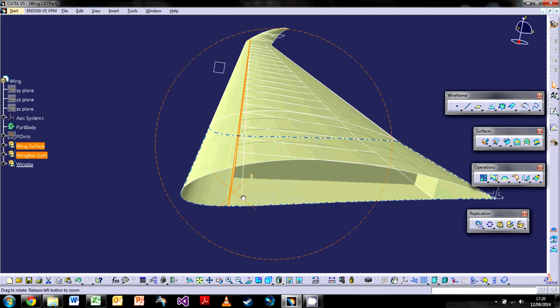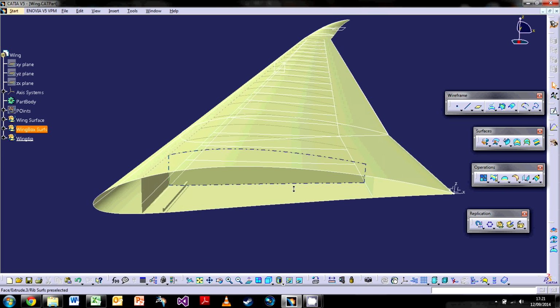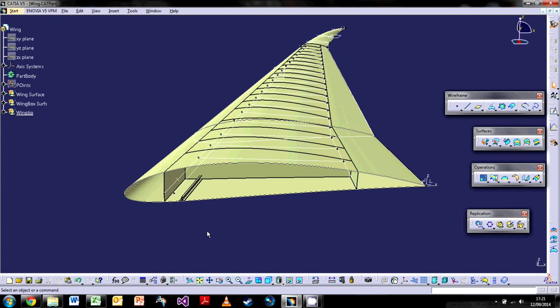Now that's a good way of doing it, because specifically it replaces the links that are from other elements, such as the ribs, the spars. It replaces them explicitly. If you change something or just move a sketch to another place, you can miss some links, or some links can be broken, and you could find it quite difficult to fiddle around with everything to make everything the same as it was. So that's just a small tip in terms of replacing your sketches.